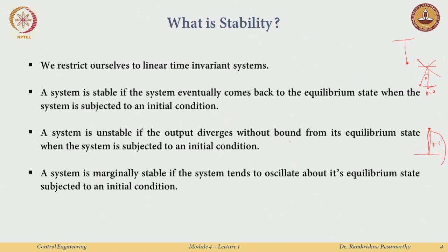So what it does, it just goes down, and then its energy increases quite a bit. Most systems do not really go out of bound because of this physical limitation, but mathematically we will say the system is going out of bound. This system, what we call the inverted pendulum system, is unstable in a way that, if it starts with theta equal to 180 degrees, this is also an equilibrium position, but this is unstable behavior.